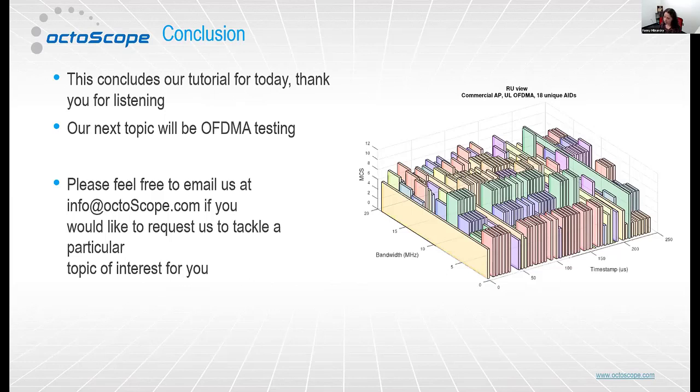And then you have a question about the maximum attenuation that the device can be set to. Our attenuators are set to a 90 dB range in half a dB step. So our range in the testbed is pretty much from saturation to disconnection. So you can really torture your device.